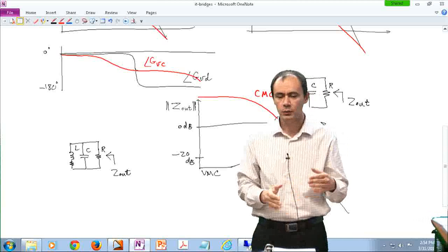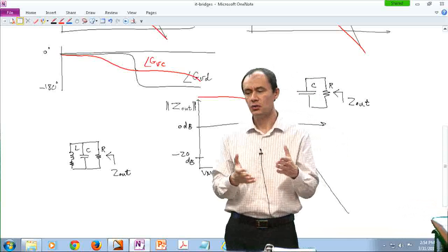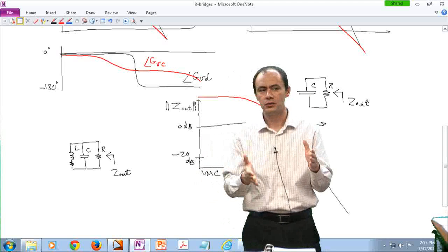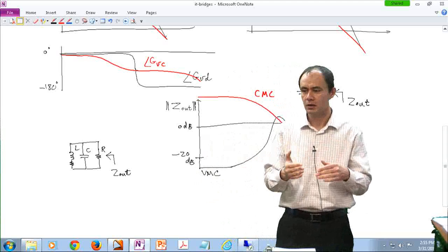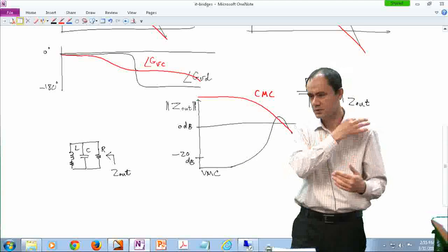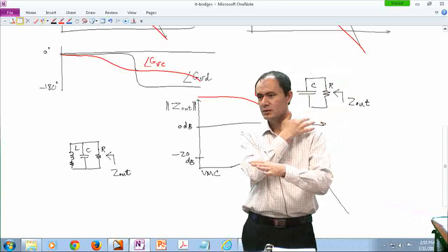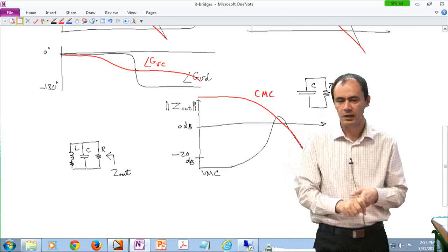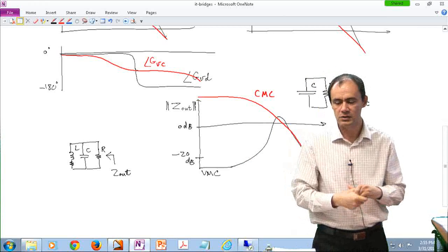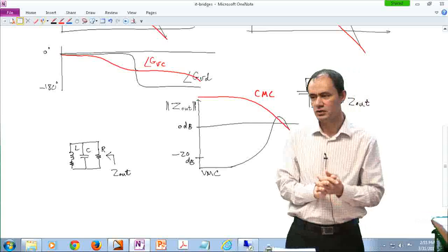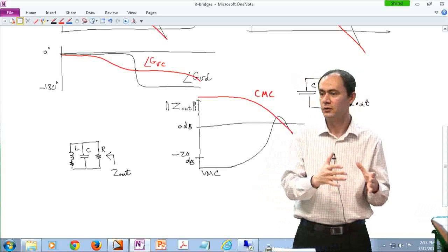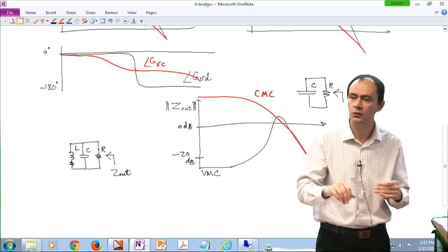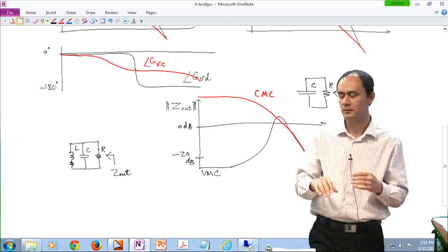All right. Now your output voltage should be very small. If your current is too high, your output voltage should be very small, because current times voltage represents the power delivered to the CPU and the losses that happen in the CPU. Okay. And unfortunately, in those regions, your converter is not very efficient, but the CPU is the priority for you, so you feed it with a very low voltage and a very high current.